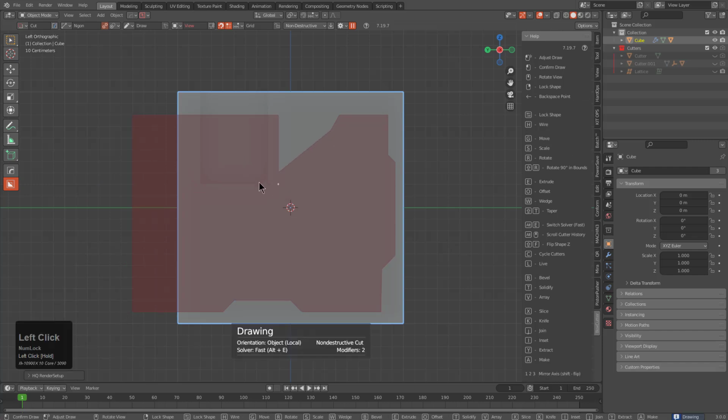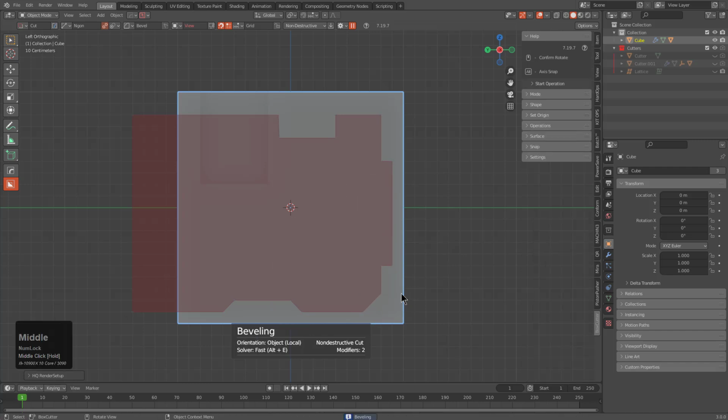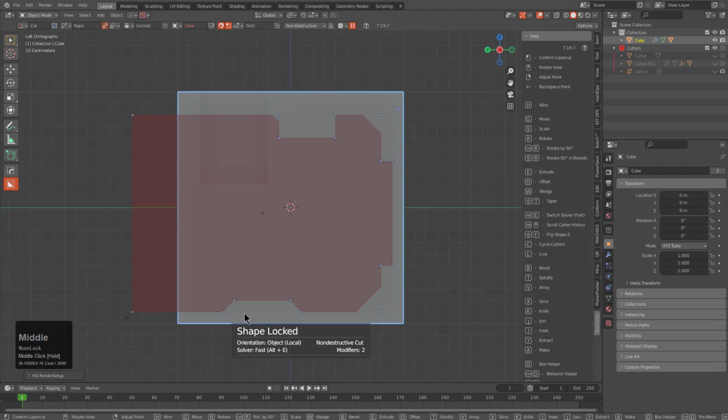Another thing is that even in the process of translating dots, which was recently added, we can hold Control to bring up grid and actually use the grid in order to orient ourselves to a static grid system in the event that, you know, we are needing to get fine with our alignment during this translation process. So I'm just snapping these to the nearest points to just kind of block them off. And then of course, like discussed in previous sections, I could bevel this point even further than that first point, or to whatever amount that I need in order to get this shape to be specifically what I need it to be.